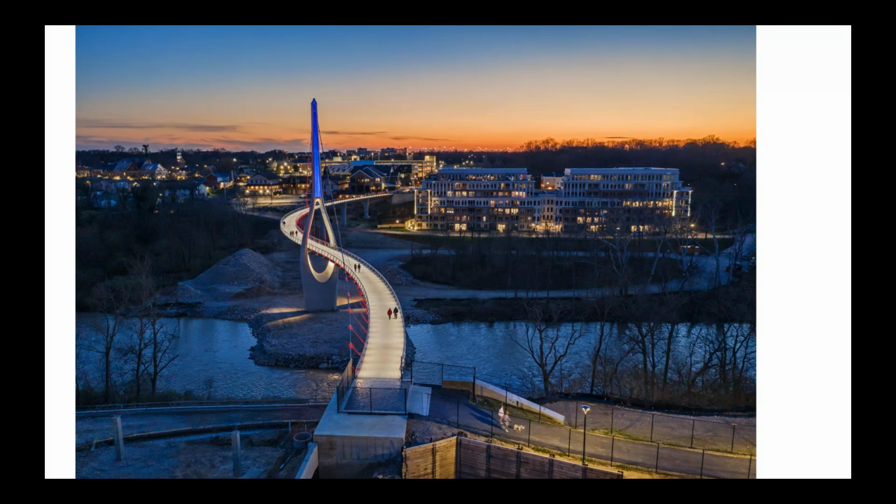And here's another question. Does the presence of the dampers interfere with the access inside? Yeah, we do have inspection access to the inside of the bridge. The 2 mast dampers were placed at the midpoint of each of these spans, and we included access openings through the web of the girder on each side of those dampers, and through the deck of the bridge we have a crawl space that workers would be able to get inside and then crawl along the length of the bridge. It's very small, as I mentioned.